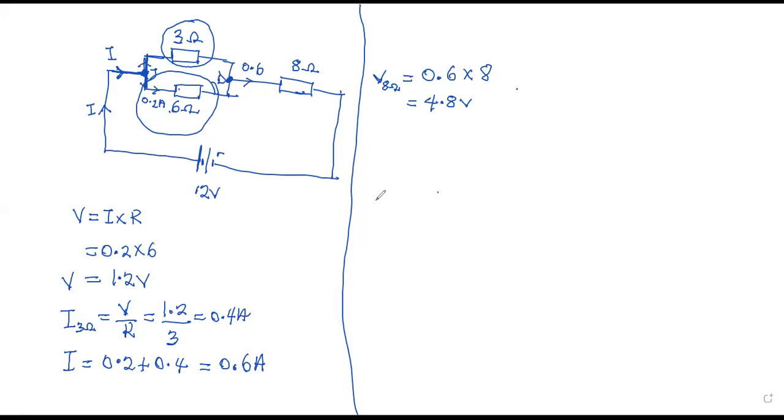Now, you see, here we are given the internal resistance. If we are not given the internal resistance, then we can just sum up the PD across the parallel and the series to be equal to this. But because there is an internal resistance, whenever current flows through it, there will be voltage drop by the internal resistance.